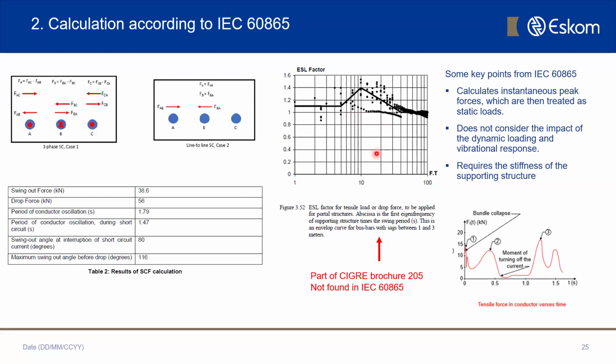So I think this also needs to be used with care. And again, it just reveals the importance of trying to get something within structural engineering codes. Another thing is that this particular calculation requires the stiffness of the supporting structure. There are a range of stiffness values that are found in the design code. So if an electrical engineer is going to use it, he might use either extent of the range, but again, you're going to have either an over design or an under design.